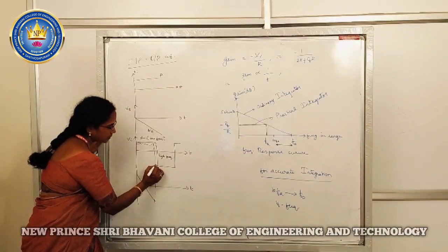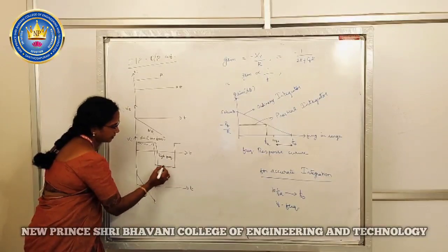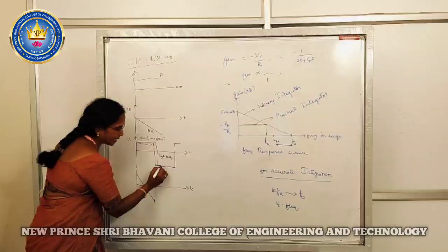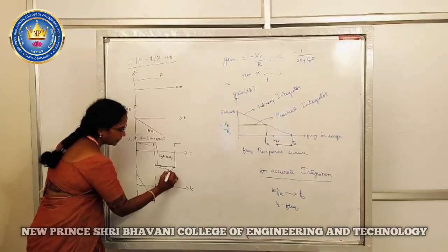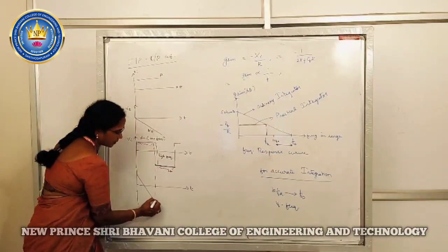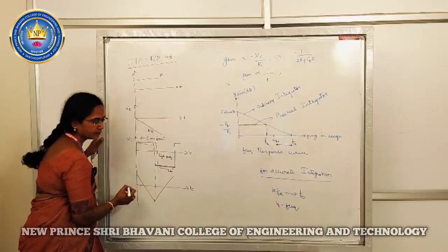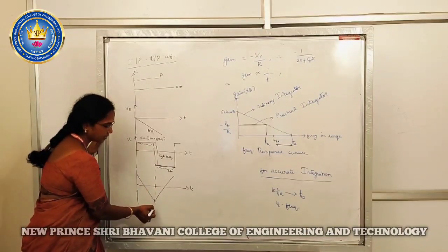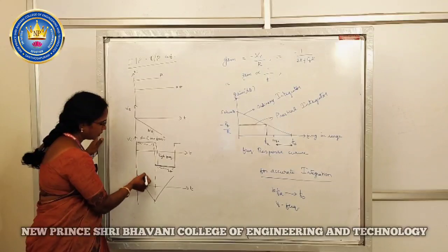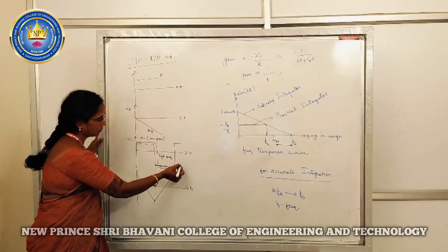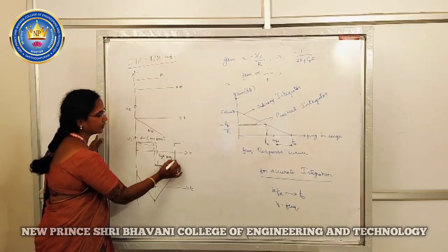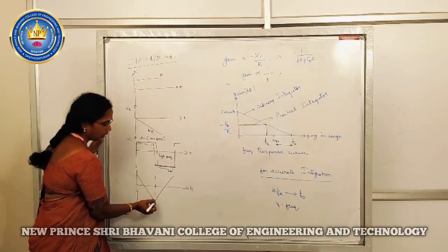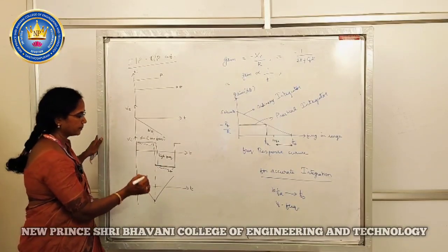Once the input signal varies from this time to this time, that is, once the input signal has low frequency, the output will have a positive ramp. So only for the low frequency signal, the output changes from negative ramp to positive ramp for the positive half and the negative half. During the high frequency component, there is no output; it is just a point.